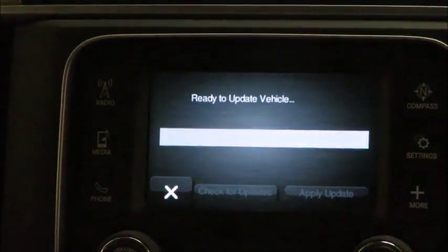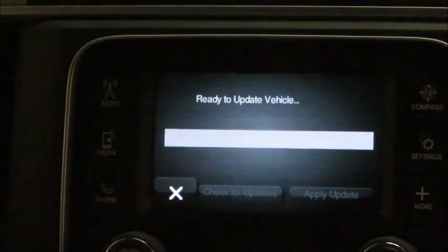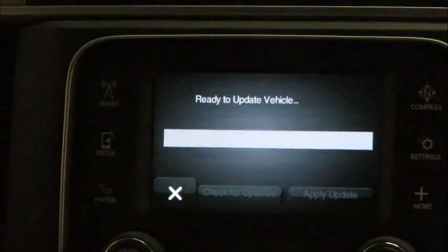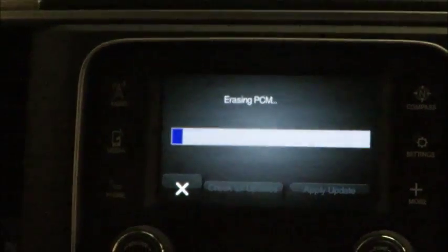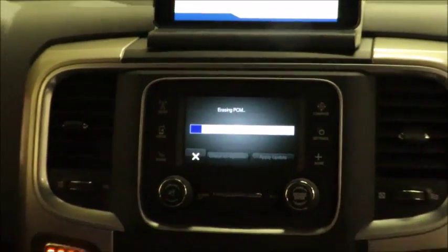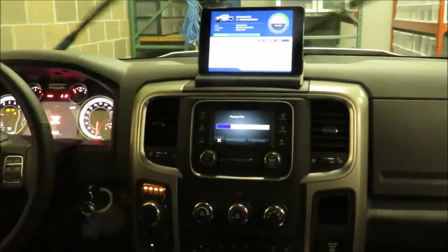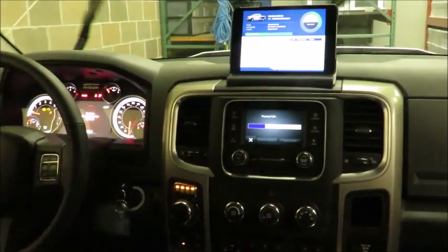The OTA client will then perform the scheduled update procedure. The first action we perform will be to quiet the vehicle network. We perform this task to increase the speed of the update across the vehicle network, as well as to improve its robustness. This step is configured and may be dependent upon which modules we are updating.